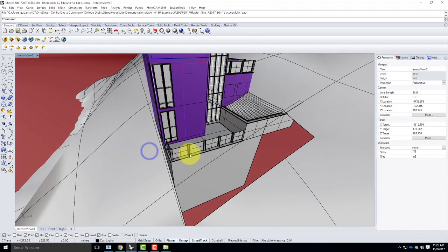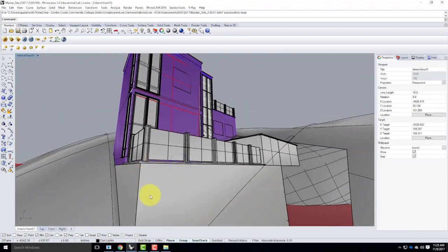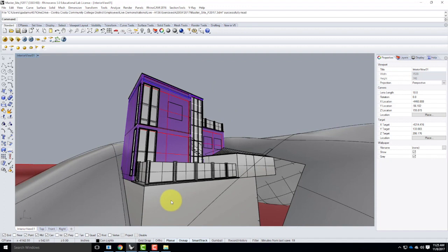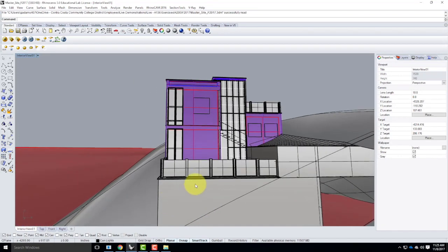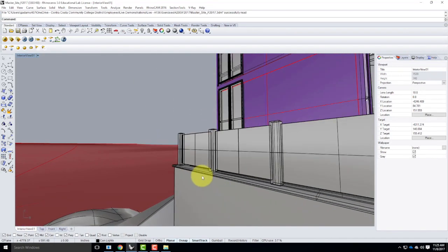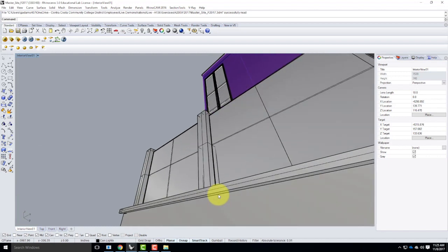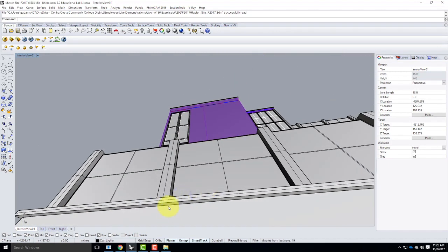One of the things that people have done in the past is they've done subtle lighting, kind of washing down the surface of a wall or a building, and that's where a rectangular light can be particularly useful. And so in this context here, I'm going to put one underneath this lip right there on the edge of my building. And in this area, I'm going to assume that the fixture itself is unseen. So it's a hidden fixture. So I'm just going to put the V-Ray light in.